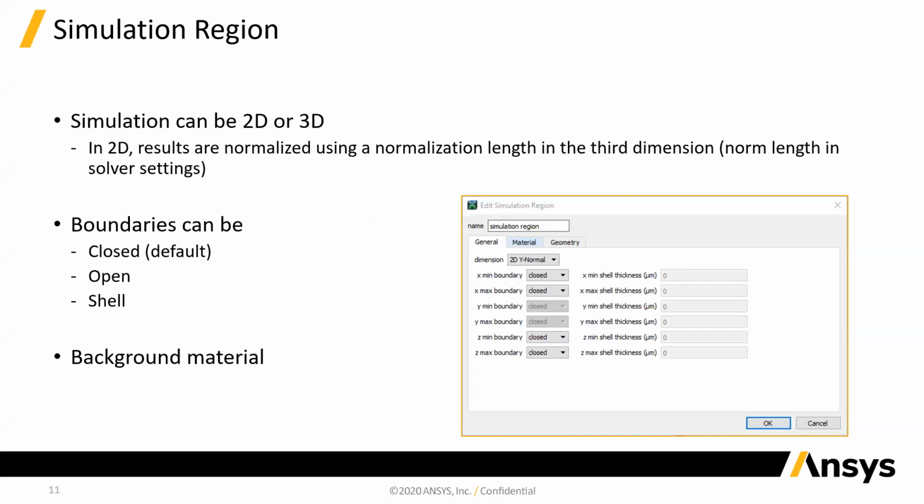And then once you have built the entire design, you can use a 3D cube to define this simulation volume. The simulation can be 2D or 3D. So again, it can be a rectangle or a 3D cube or pyramid. And then you use that to define how much of your actual geometry you're going to simulate.